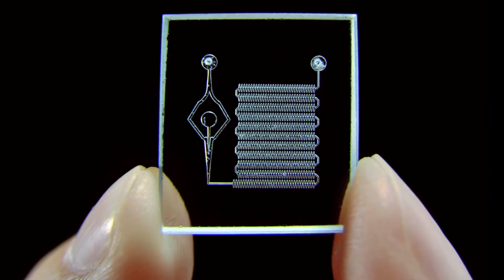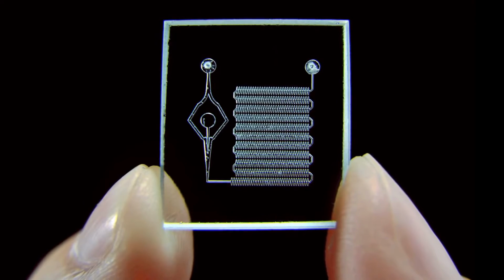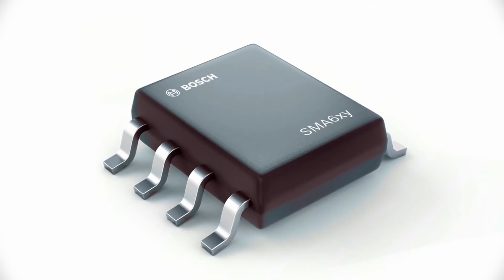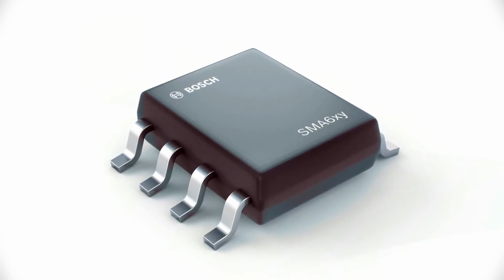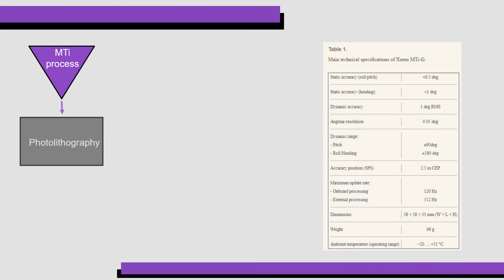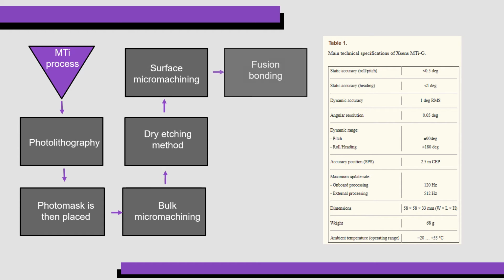Finally, the only thing left to do is the assembling and packaging part. Assembling and packaging complex microscopic parts is extremely difficult, as conventional automated assembling and packaging is not suited to such a micro level. To date, many MEMS devices required individual handling. We can see more general process methods on the next flowchart and some of the characteristics of the MTI that we choose.